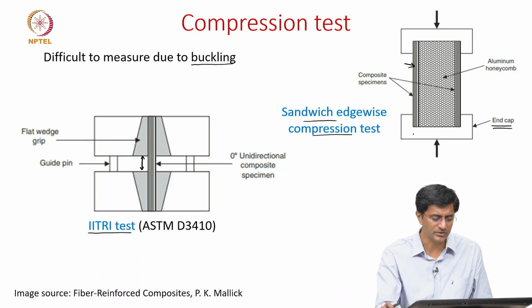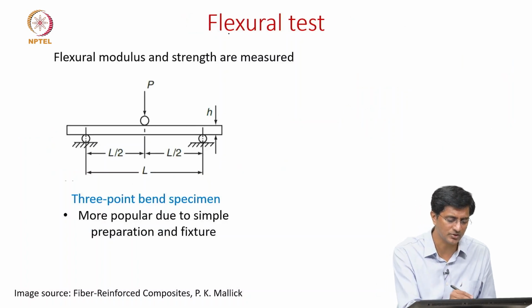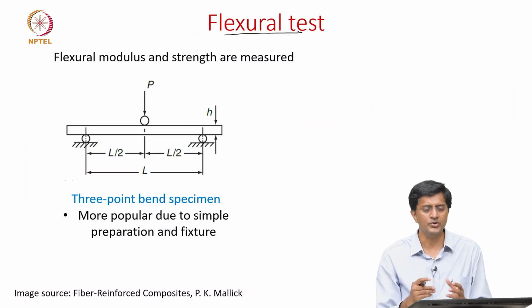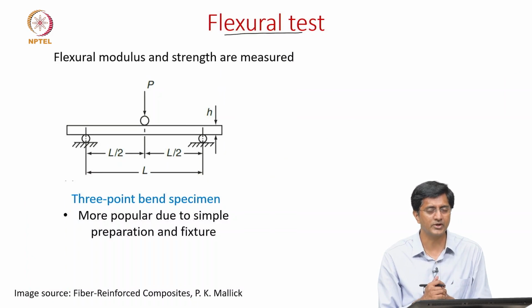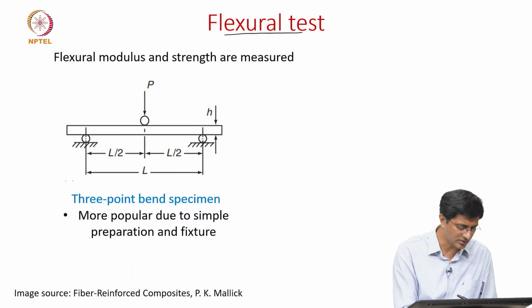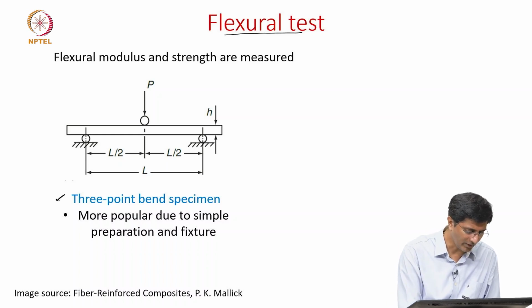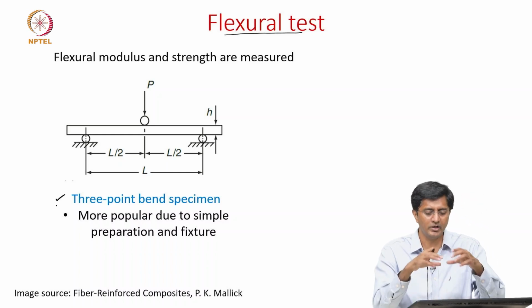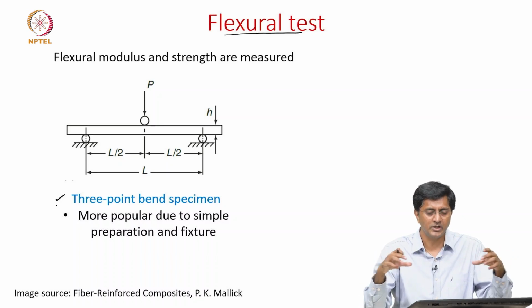So after this, now let's look at the flexural test. Actually, in composites, most often people go with the flexural test because these are very simple. The specimens are simple to prepare, as well as the test procedures are also more straightforward. So usually it is done using a 3-point bend specimen, where you have a composite laminate in the form of